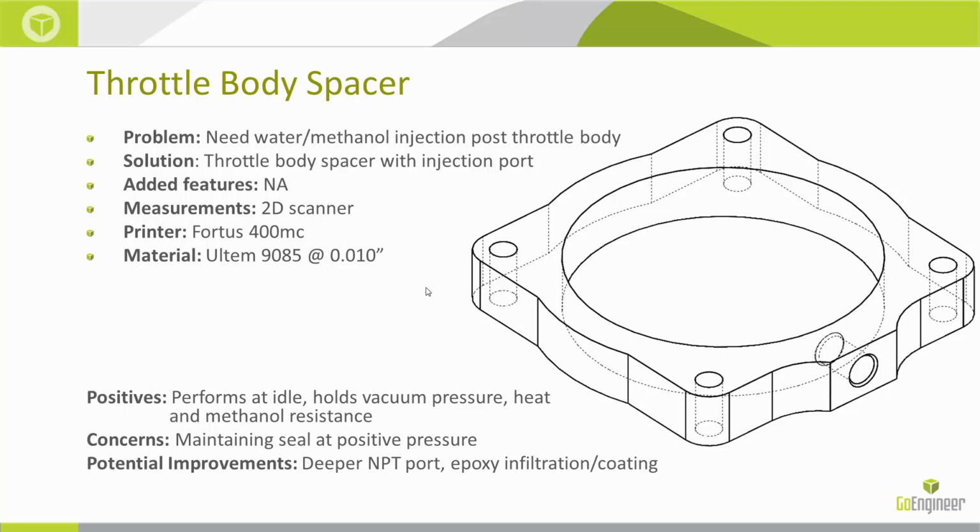I'm not 100% certain how long I'm going to keep this in, but this is supposed to be a prototype, because I'm going to have to get one of these made eventually out of aluminum, or I could do some more processes to this as far as, say, infiltrate it with epoxy or sleeve it, and it could do a good job. Infiltrating the epoxy would be more for allowing it to hold pressure. That's one big concern here.